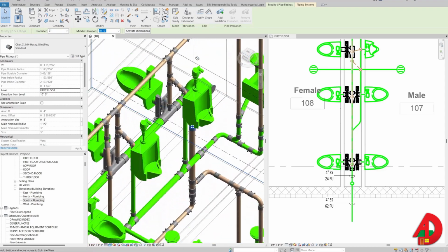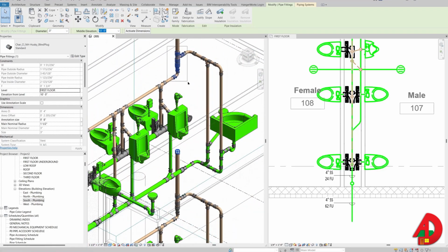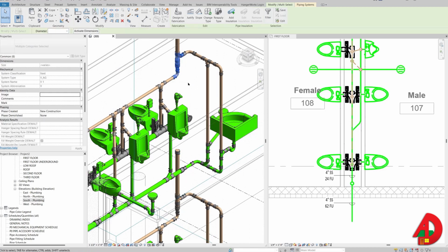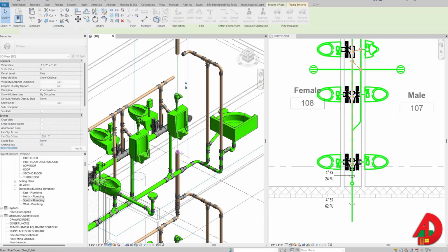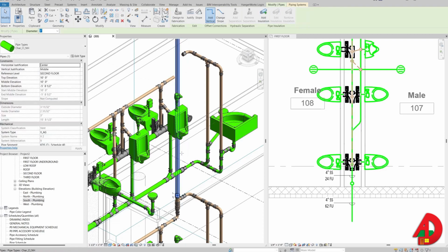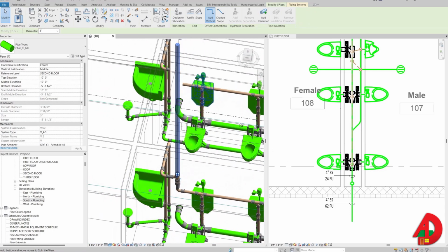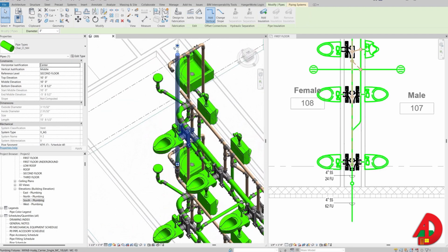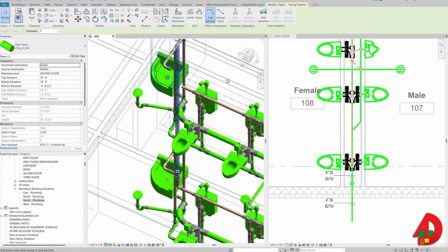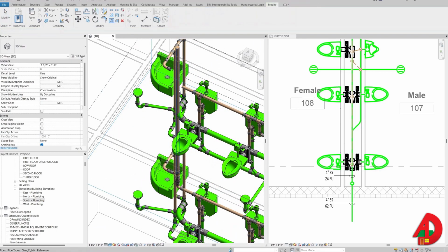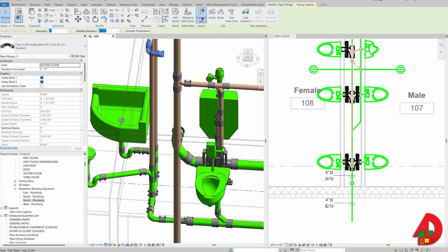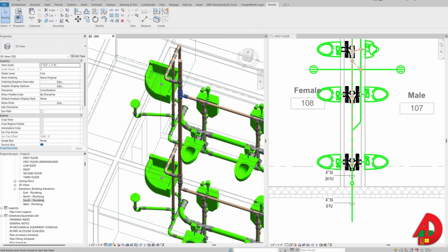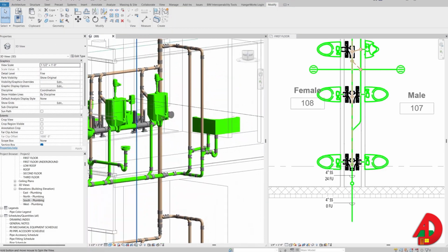I also have to connect the vent riser, so I will make a square selection to delete these elements. Also, I need to get rid of this cap, and then I will drag the top pipe all the way down till I see the purple circle that hints I can connect to the center of the pipe. Now I need to extend this line to connect to the riser, and also this fitting will have to connect to the riser. But it seems that there is a clash here with the wall cleanout.